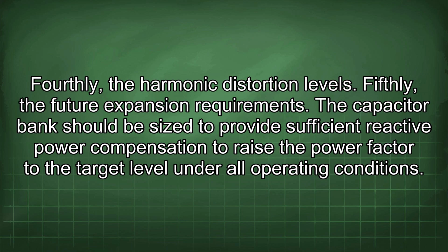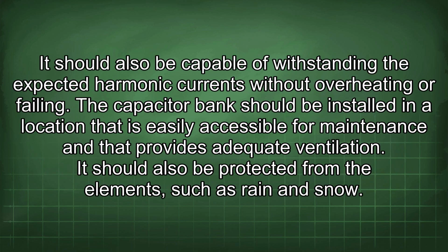The capacitor bank should be sized to provide sufficient reactive power compensation to raise the power factor to the target level under all operating conditions. It should also be capable of withstanding the expected harmonic currents without overheating or failing. The capacitor bank should be installed in a location that is easily accessible for maintenance and that provides adequate ventilation. It should also be protected from the elements such as rain and snow.